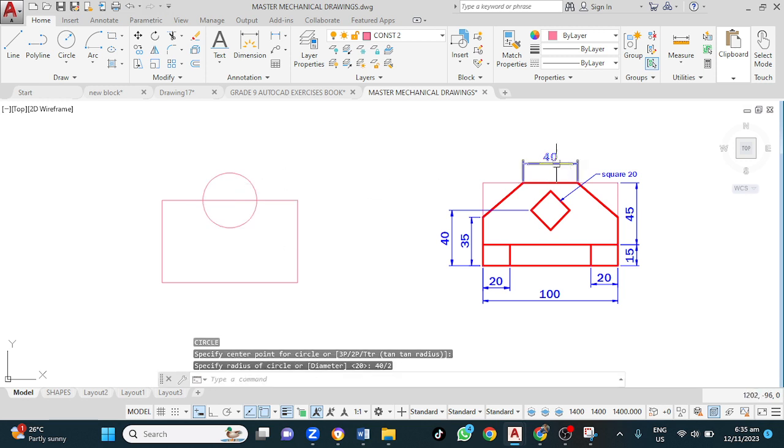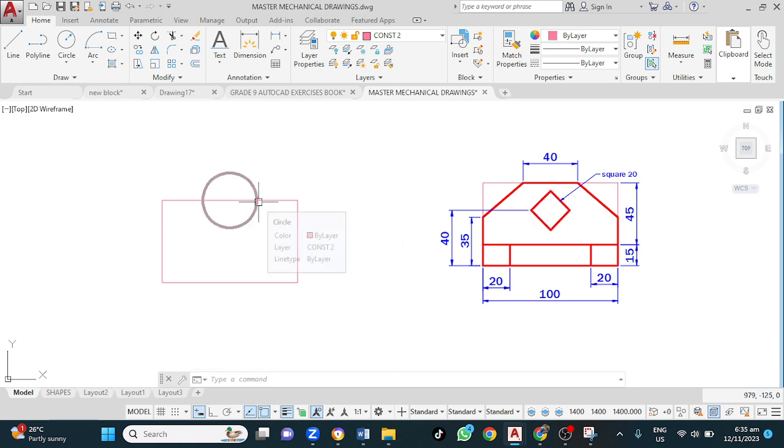So what I just did, I typed 40/2. That actually divides the diameter by 2. This is useful in cases where the number doesn't give you a nice square radius. So this is now used to determine this point here, that point there.